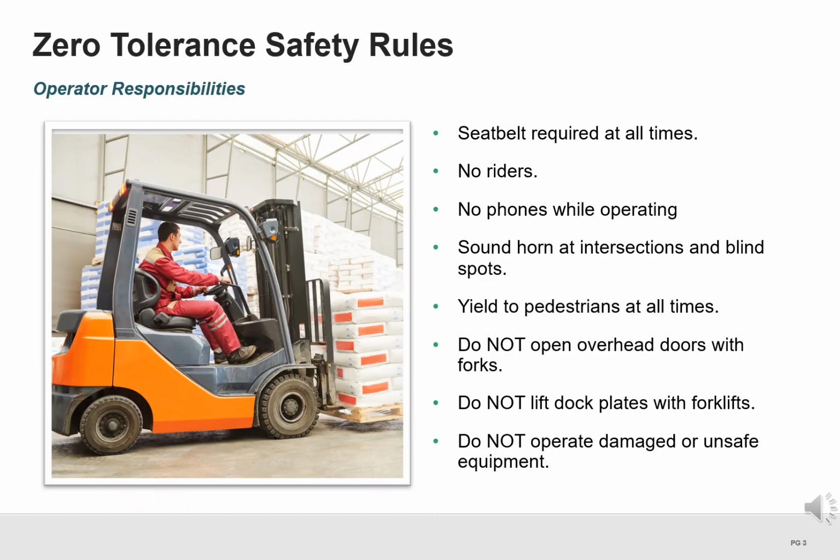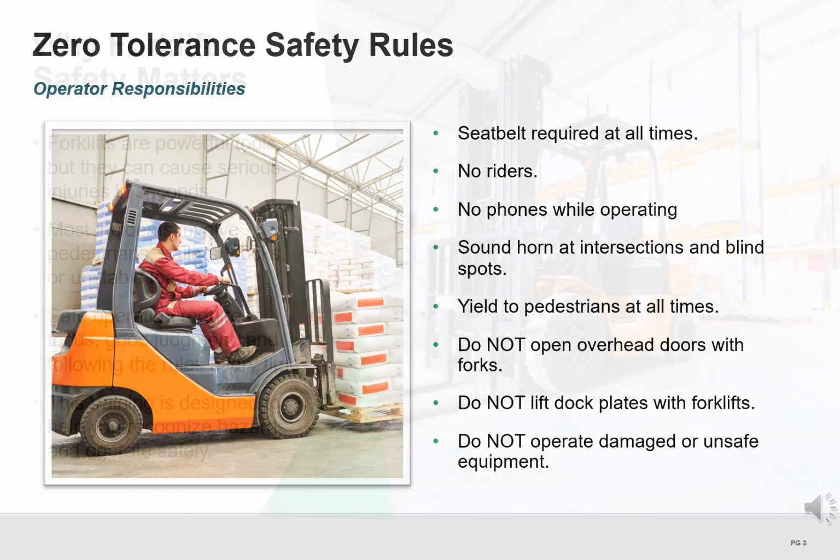Pedestrians have the right of way. Operators must stop and yield. Forklifts are never to be used to open overhead doors or lift dock plates. And if a forklift is damaged or unsafe, it is not to be used. These rules are in place to prevent serious injuries.